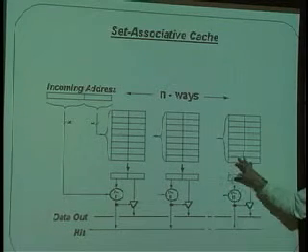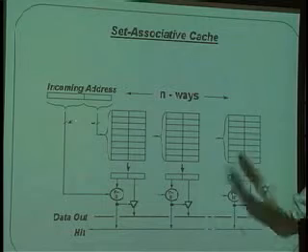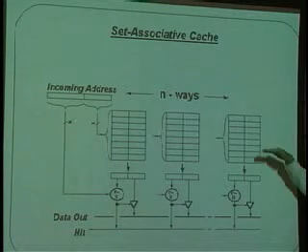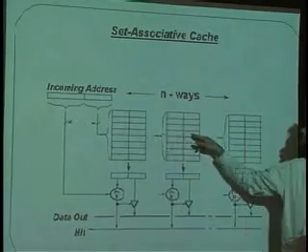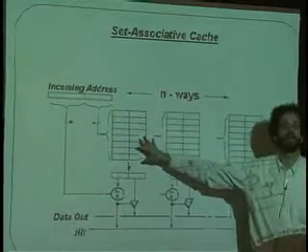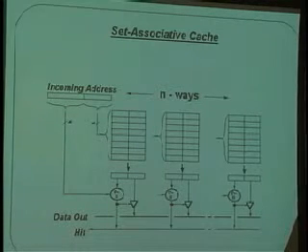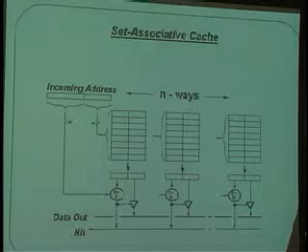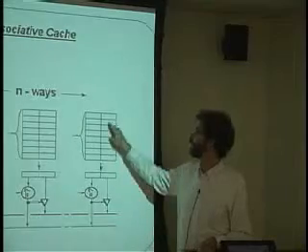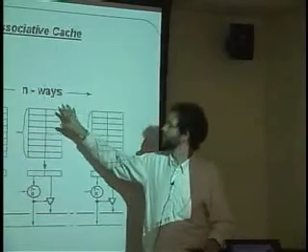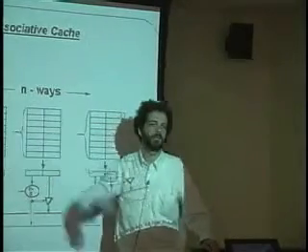It's not fully associative. It's not the case that any piece of data from any address in the main memory can reside anywhere in this cache. The low order bits still constrain a particular piece of data to reside in only one row. But there's complete freedom as to which column, which of the n ways, it can live in. So if we have 3 areas of activity that happen to have overlapping low order bits, this architecture can accommodate it. For instance, the stack could use this one here, the program counter could use one here, and something else could use one here.